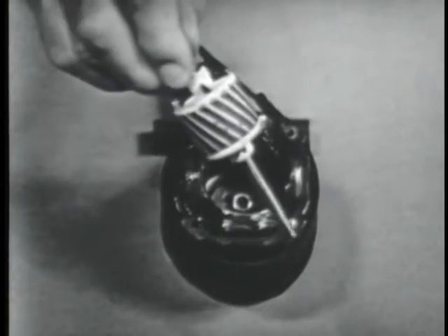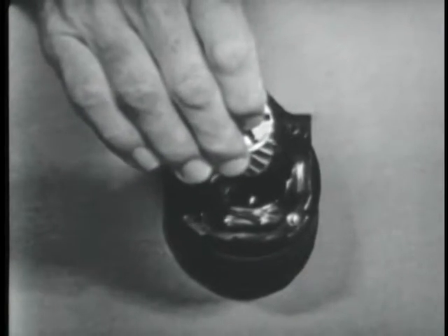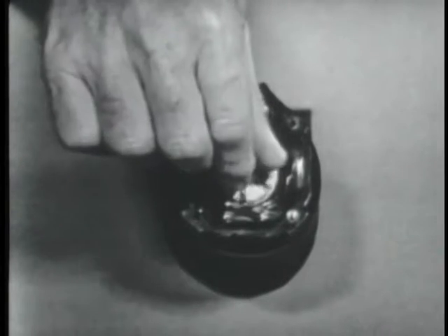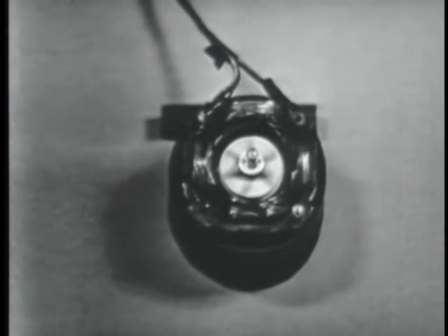But watch what happens when the rotor is placed inside the field windings. And the power is applied. The rotor rotates. Now, it's not physically connected to the field windings in any way, but it does rotate. Why? Simply because the field windings are providing a rotating magnetic field that induces a voltage into the rotor that causes current to flow, and the rotor becomes an electromagnet. And once it's magnetized, it's got to follow the rotating magnetic field, just like the compass needle did.